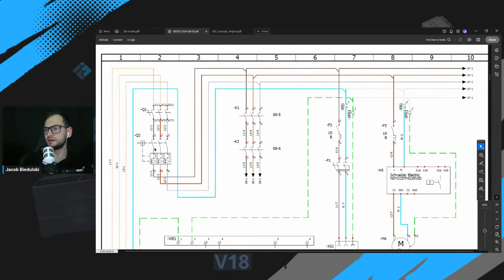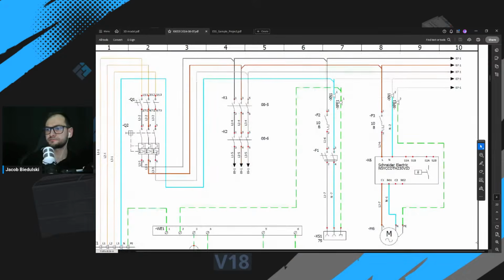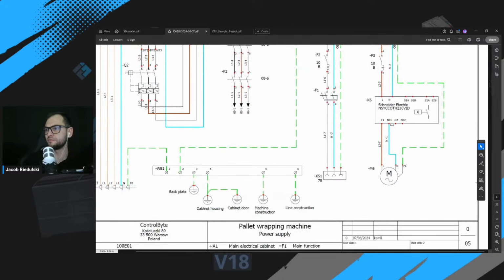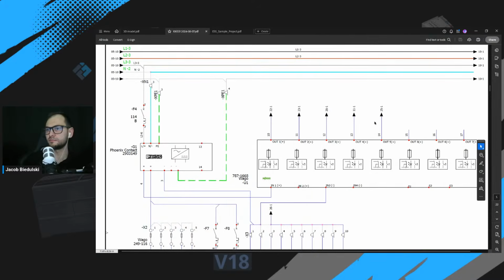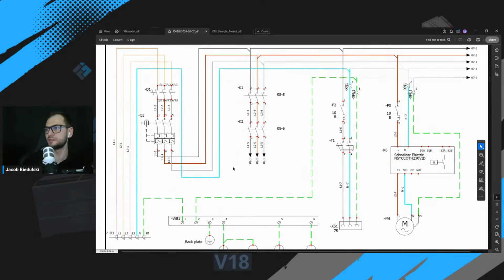And after that, the power is connected to, for example, main safety contactors, K1, K2, to the circuit breakers, and so on. Then to 24 volts power supply, and it powers the PLC system in our control cabinet, okay?